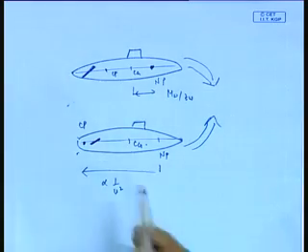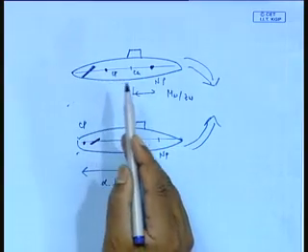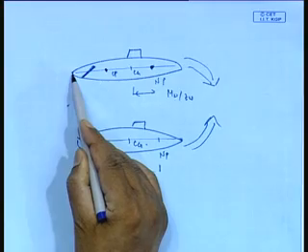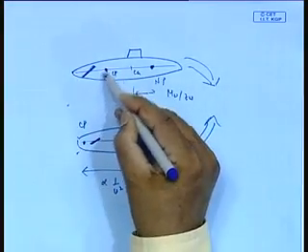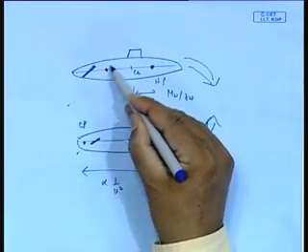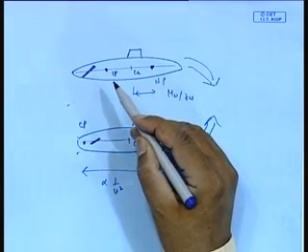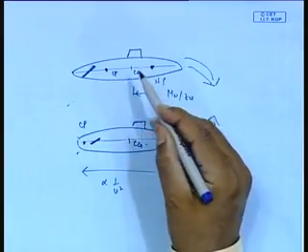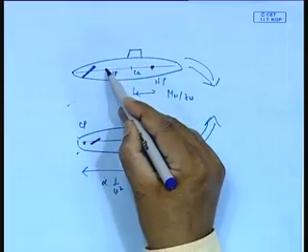So naturally, what is happening is that at higher speed my Cp is somewhere here, but as I go to lower speed, my Cp keeps shifting back. Now, what is happening at Cp itself? As I mentioned earlier, if I keep a stern plane and turn it, it is essentially not changing depth, only angle. Remember what happened. I will come to that again later.